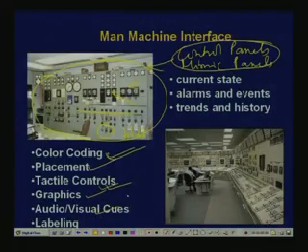Then the various controls should be such that the operator can very closely operate it. So, you have various kinds of joysticks and other controls where the operator can conveniently give manual control commands. Of course, graphics, audio visual clues, alarm annunciations. So, some lights glowing, some hooters, and proper labeling, that is each variable should be properly labeled, so that the operator can quickly make out the situation.